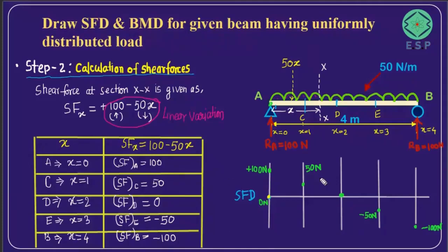So now I can plot the variation. Okay, let's see how it looks like. So as you can see that the shear force goes from 0 to 100 newtons like this, and then it goes from 100 to 0 over here till point D, from 0 to minus 100. Okay, and now as you cross the point B, like if you put your section somewhere here, so this minus 100 which was here, now this also will be included. Just left it was minus 100, it was coming.